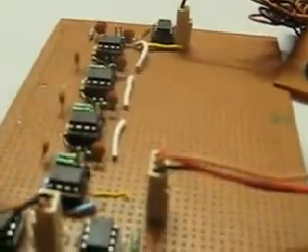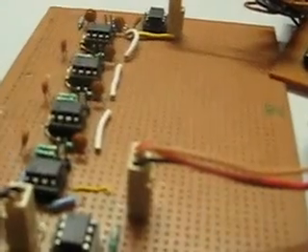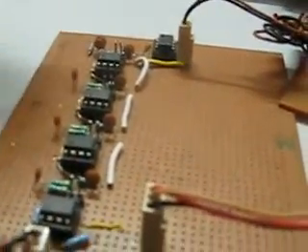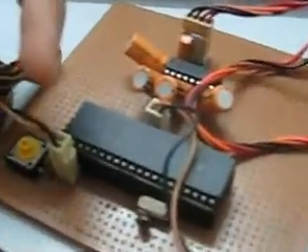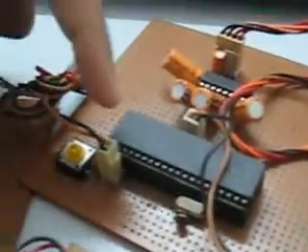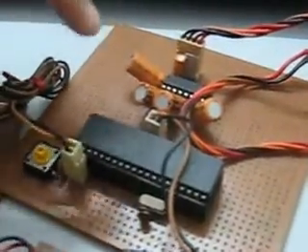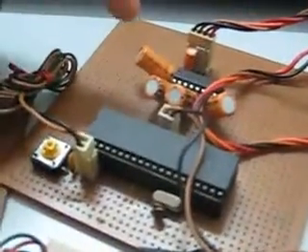Then for a clear view of the ECG signal, we have to make the filters. So we have designed a 6th order Butterworth filter and a notch filter. Through this, we are transferring the signal to the PIC18F4550 microcontroller, in which the analog signal is converted into a digital signal, and then for serial communication we are transferring the signal to the MAX232.